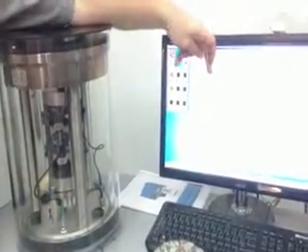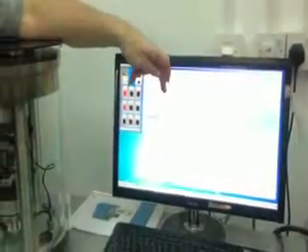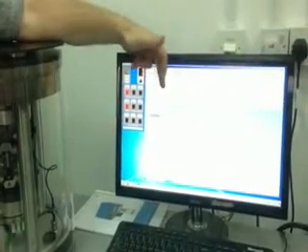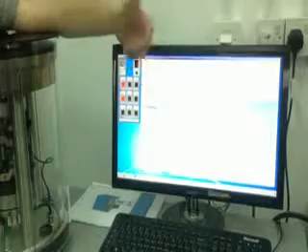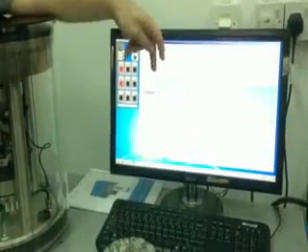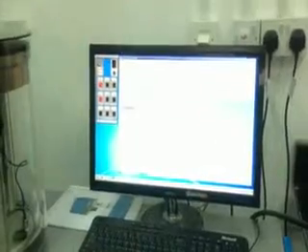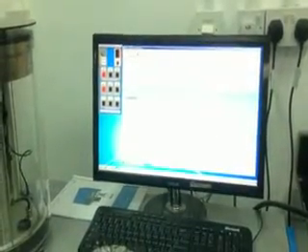So all you would need to do is enter your initial, estimated modulus value. If you're doing fixed frequency temperature ranges, you could save your different templates with these parameters in there, so you don't have to continually re-enter all your information. The gauge length is here. Yeah, so 70 mil gauge.